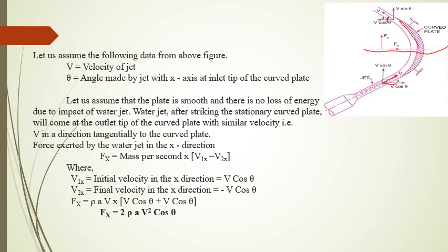Here the plate is smooth. So therefore there is no energy loss due to impact of jet. Therefore the velocity at the inlet and at the outlet be same, that is V. Force exerted by the jet in the direction of x-axis. Here in the direction of x-axis, this is x-axis Fx and this is opposite to the direction of jet.